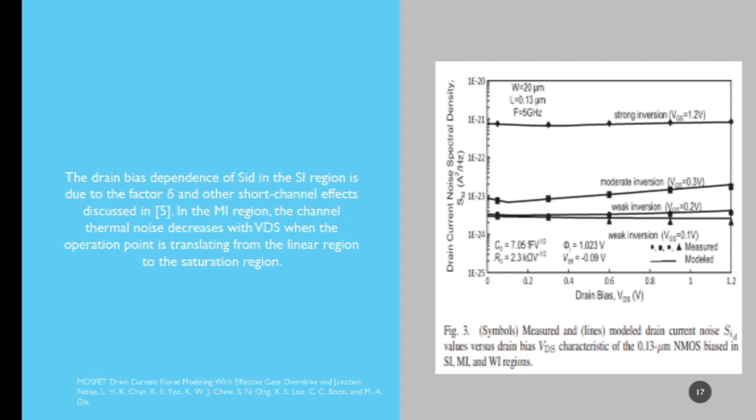And in the moderate inversion region, the channel thermal noise decreases with VDS when the operation point is translating from the linear region to the saturation region.